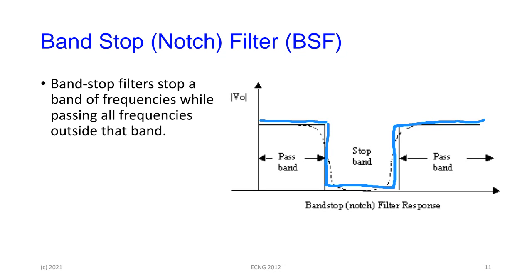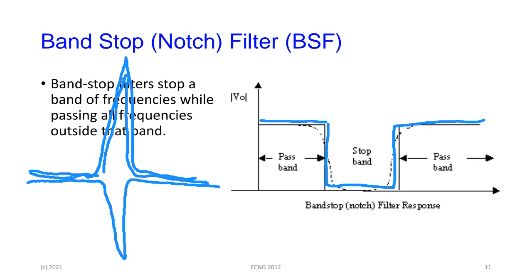So once the feedback starts, you have a frequency, and then at some point a very high pitch will start to develop because somebody's microphone is too close to a speaker. Then you have the amplitude of the sound going to the speaker, and it suddenly starts to peak very high at a particular frequency, which is the whistle that you hear. What the system does, or the person on a mixing board, for instance, will do manually, is to put a notch filter right here. So it's passing everything and notching out this particular frequency, in other words, rejecting it.